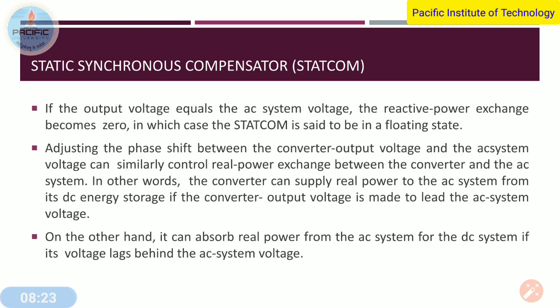Now, this is the third case. We can consider that if the output voltage is equal to the AC system voltage, then what will happen? So in this case, the reactive power exchange becomes zero, and the STATCOM comes into a floating state. So it will neither generate reactive power nor consume reactive power. So it's in the floating state.